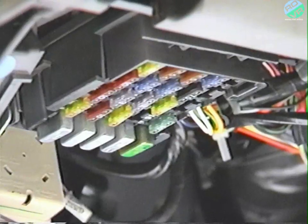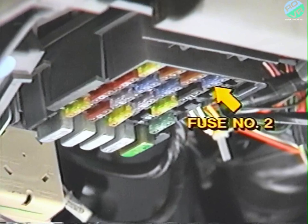Self-diagnostics is a great feature of the Premier climate control system, but in some cases you may have to resort to more conventional means to find the cause of a problem. For example, suppose that there is no heating or air conditioning at all. Your first check should be at fuse 2 in the fuse panel.